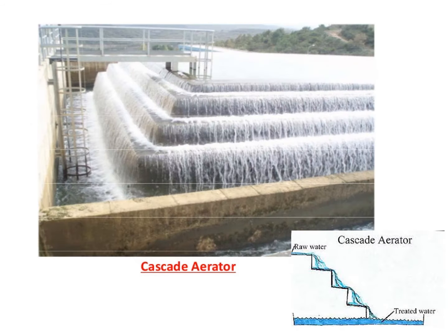Then these are cascade aerators. So basically in this, aeration is to be provided to supply air. So here it is a cascade type of aerator. Number of steps are there. Water will be passing through these different steps, and at each step oxygen is supplied from the air, and due to that natural aeration, the impurities such as odors and some gases will be removed.